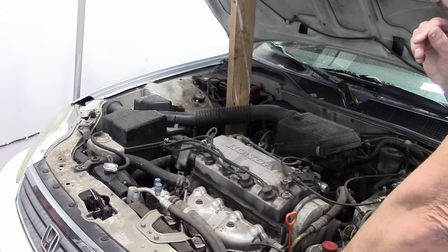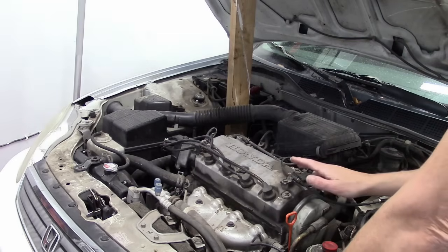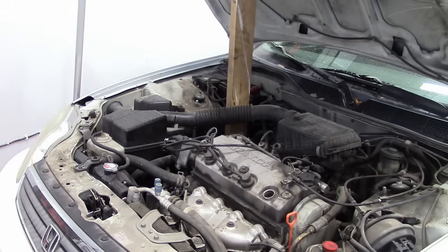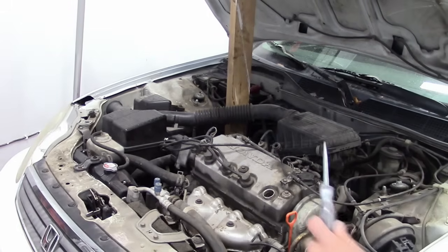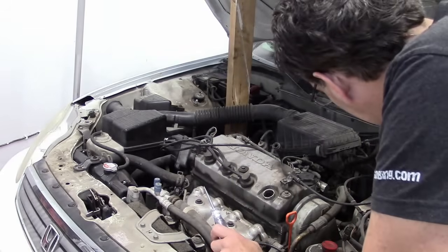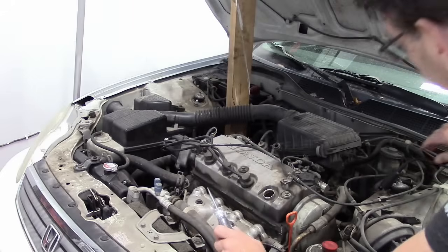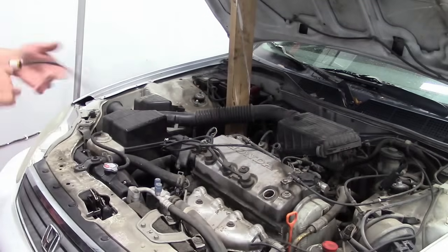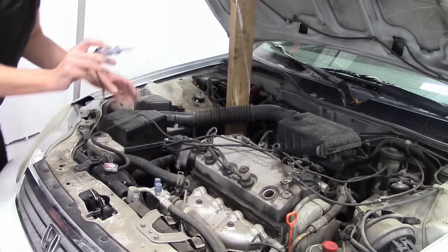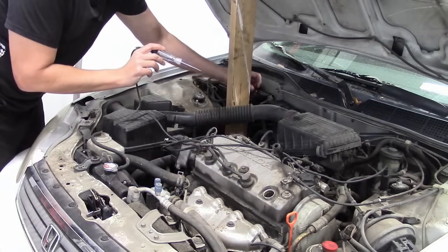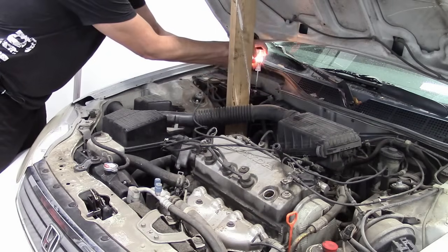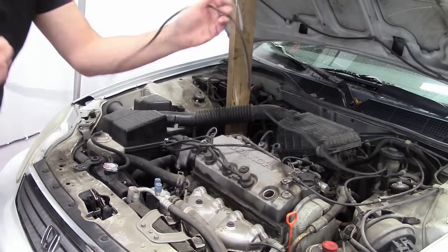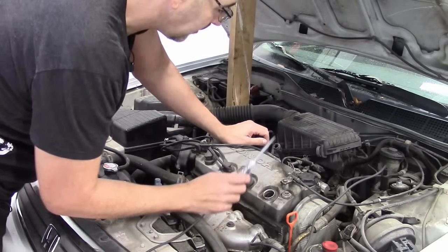So we will look at the spark next. That is what I did. Like that, and we'll put a test light up to that. So let me get a test light. All right, using an incandescent test light, not an LED one. Going to an engine ground, I'm just using one of the bolts for the shock here. And I want to first make sure that I've got a ground on my test light. So I'm going to go to battery positive, and we can see the test light does light up there. So I know I've got a good ground. That'll give something for this spark to jump to.